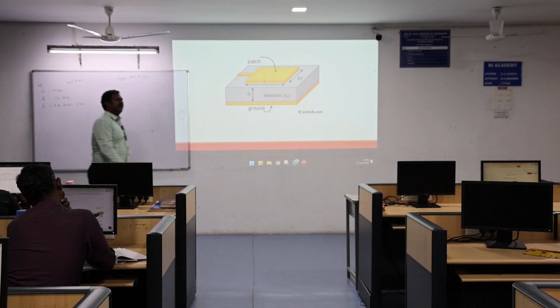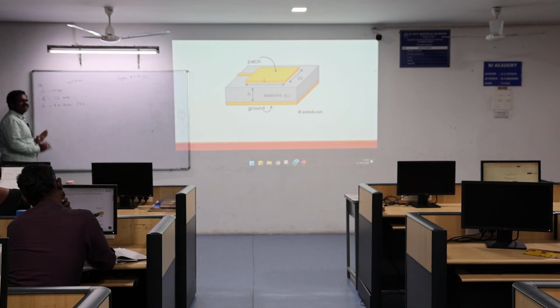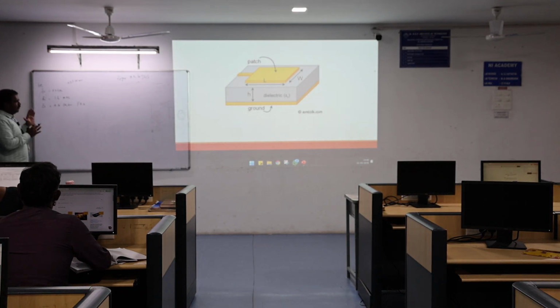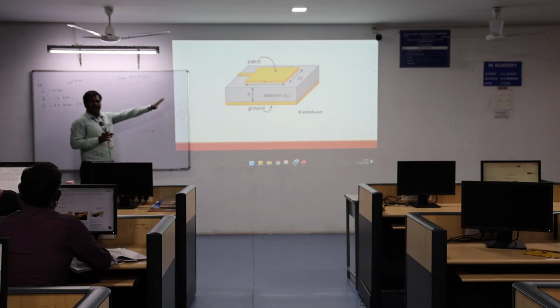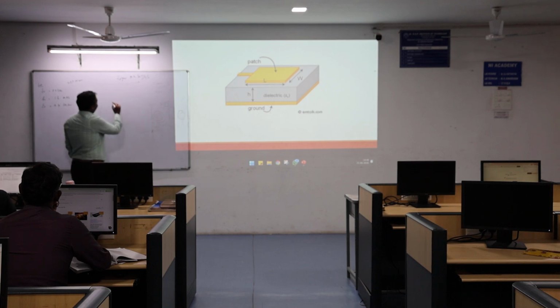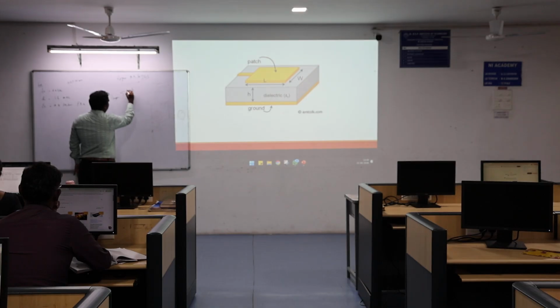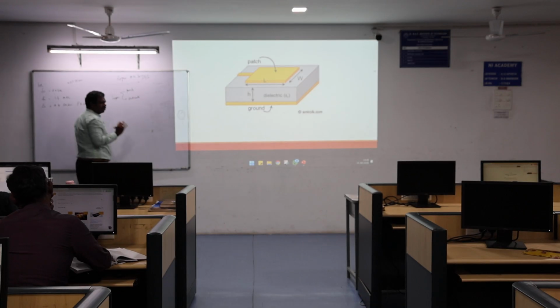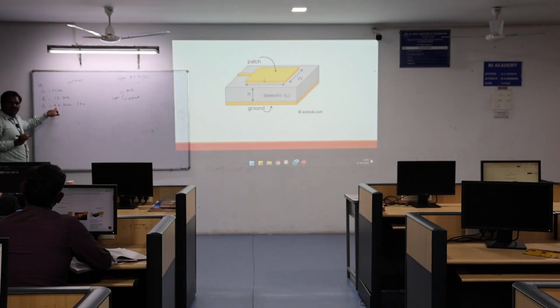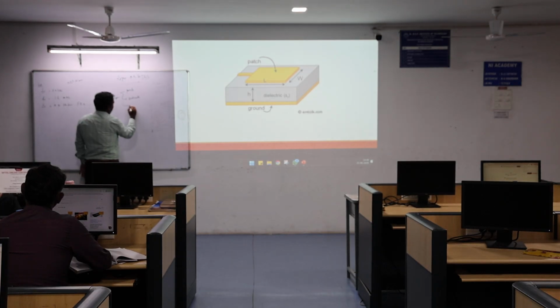So these are the 3 parameters. You only need to know these 3 parameters to design your antenna. With the help of these 3 parameters we design the entire combination of the antenna. For example, there are 3 layers. The first layer is the patch layer. The second layer is the substrate, which is already given: my specification is 1.6 thickness and a dielectric constant of 4.4. The other is the ground plane layer.